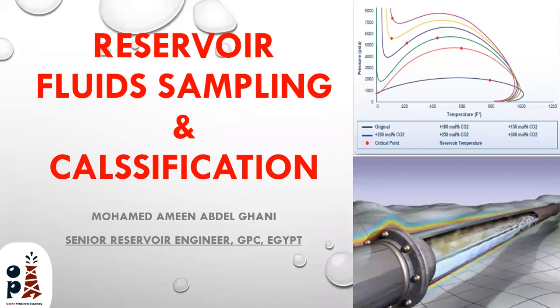For oil reservoirs, the routine experiments are the CCE or the constant mass expansion and the differential liberation and also the separator test that is done to determine the optimum separation for the production facility. For wet gas reservoirs and also the gas condensate reservoir, the CVD is done instead of the differential liberation for oil reservoirs. So the CVD is for constant volume depletion.